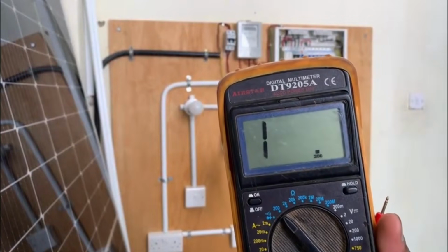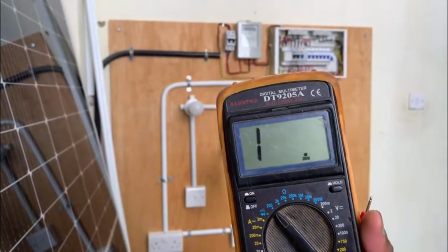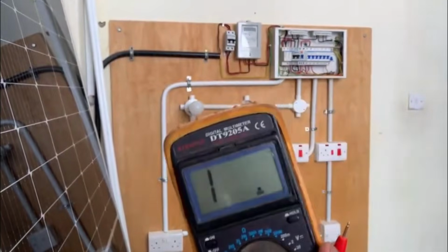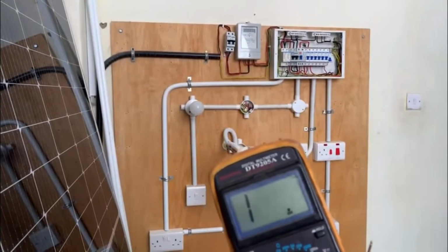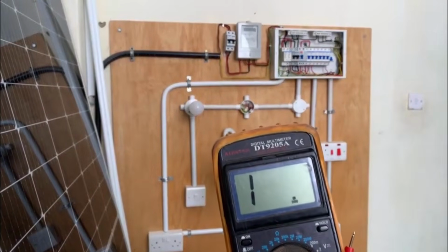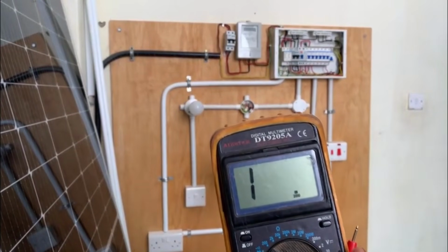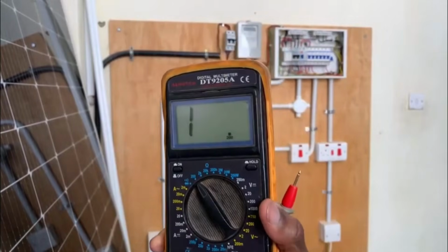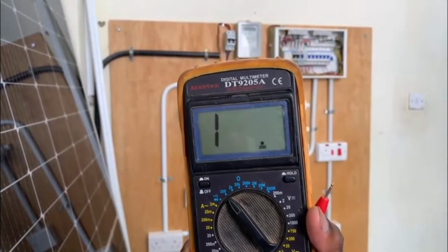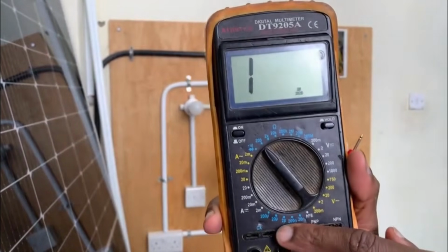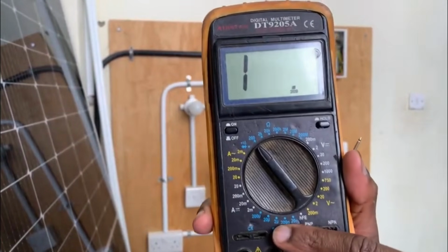And first of all, if you want to use a multimeter for current, you have to know that you will have to isolate that circuit. I hope we know that, because you have to place the digital multimeter in series with that circuit. So let's say you have current flowing through a bulb from a battery. You will simply cut that wire or disconnect it and place your probes in series so that you can record the current. Okay, this blue on this part here is the capacitance.